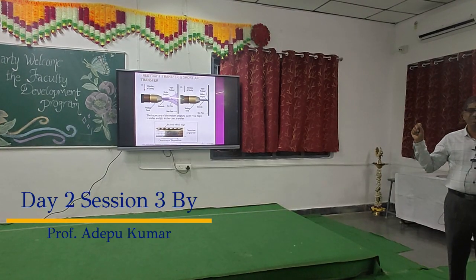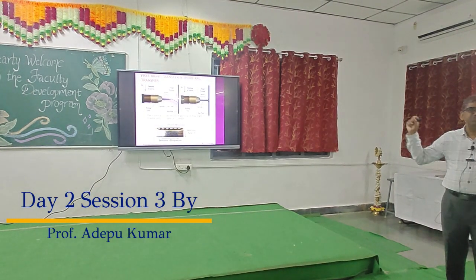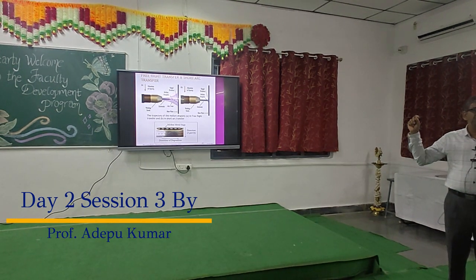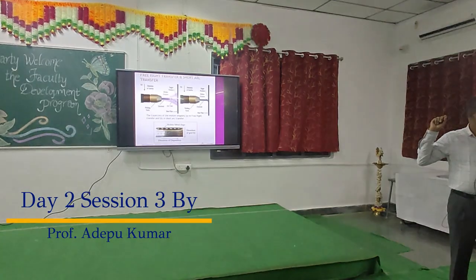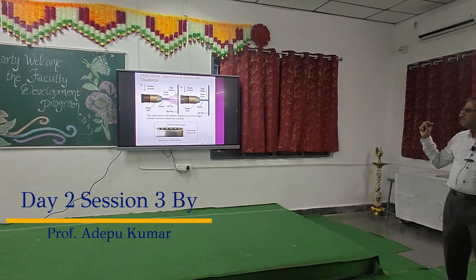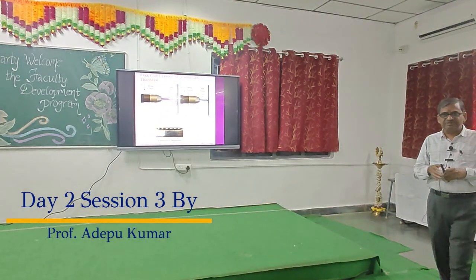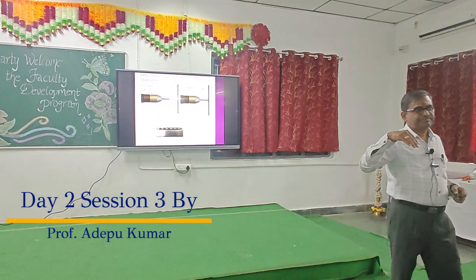You are depositing the material, not exactly, but it reached that position. So based on your experience, you may adjust your nozzle position. Then due to gravity, you are depositing the material. Let us say you are depositing material like this.